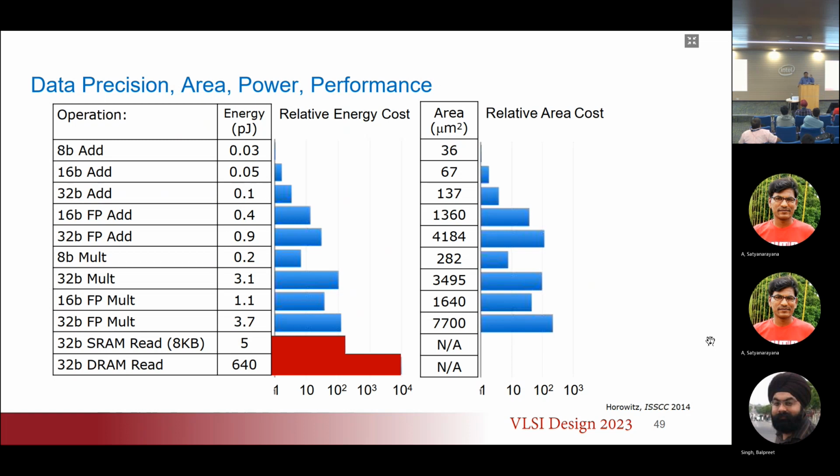So this is completely driven off this chart. As you can see, I don't want to do DRAM operations, and so I don't want to be dumb about my computation. I want to do one tile at a time, and the tile fits into my cache. And when I'm fetching from the cache, it's 5 picojoules instead of 640 picojoules, because it's an SRAM read. And I want to be finished with it before I fetch my next tile.